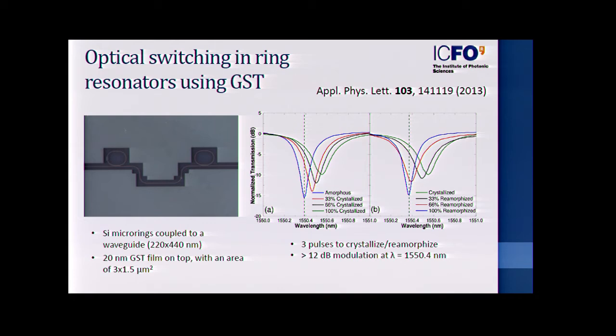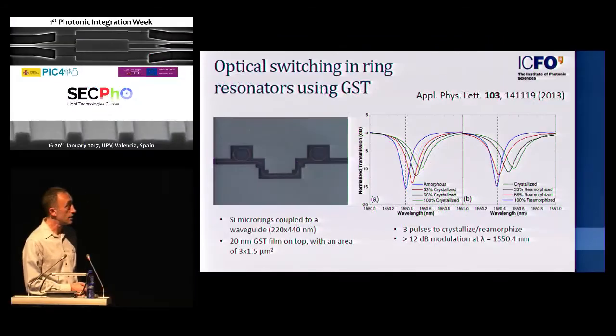They use evanescent coupling with waveguides, or I will show you other types of structure, plasmonic structures. The idea is that in that case you have a balance between the linear loss and the extra loss or extra phase. When you change the refractive index, you change the phase due to the switching of the phase in these materials. So this is essentially a microring structure in silicon.